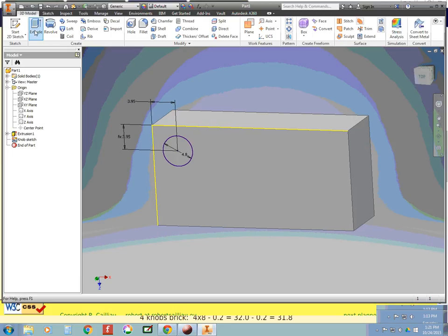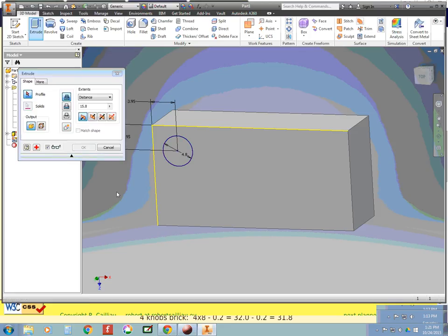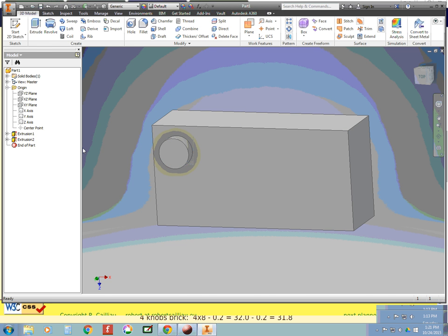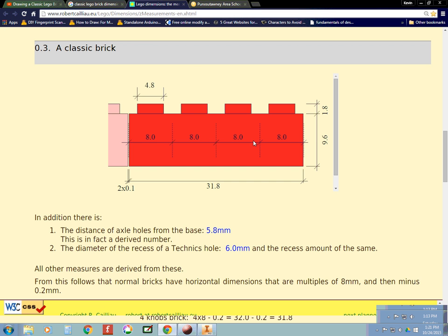And again, you can grab extrude from here, or right click on the screen and choose extrude, keeping in mind before you do any 3D modeling you have to finish your sketch. So extrude, going to choose that geometry. It has the correct direction. I want to extrude it out of the screen toward me, but I only want to make it, I believe it was 1.8. And click OK, and let's just double check that dimension. It is 1.8.